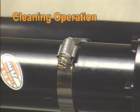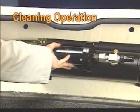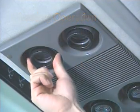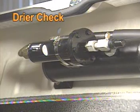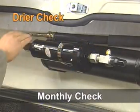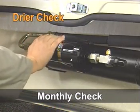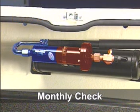As for the procedure, repeat dryer replacement 2 or 3 times after air conditioner operation. If the air conditioner gets cool enough, we may judge that impurities have been removed. When the refrigerant line is polluted, the dryer may be clogged. Dryer clogging can be checked by the temperature difference between the inlet and outlet pipes by hand. The temperature should be the same. If you can feel the temperature difference, replace the dryer. The dryer is a monthly check item.